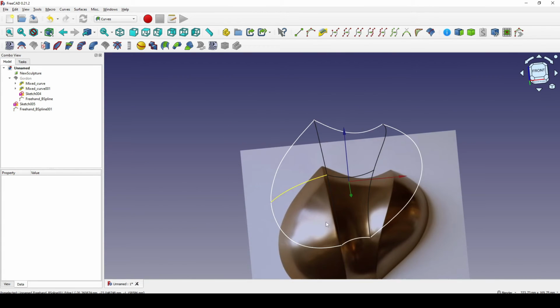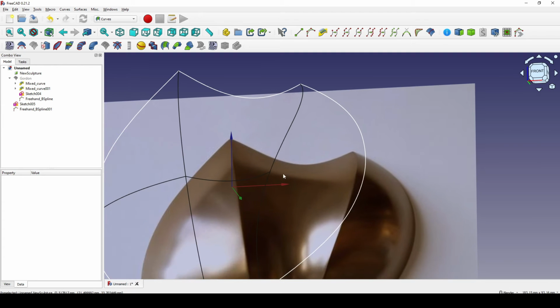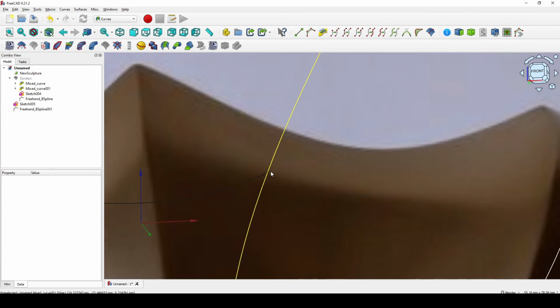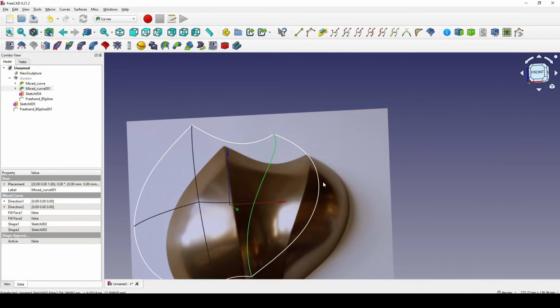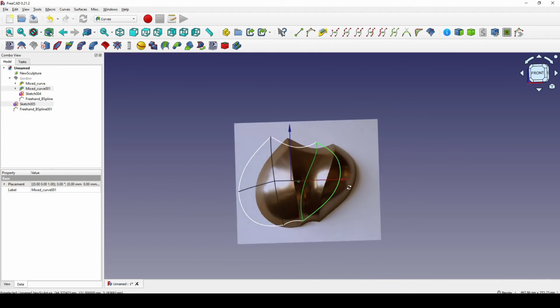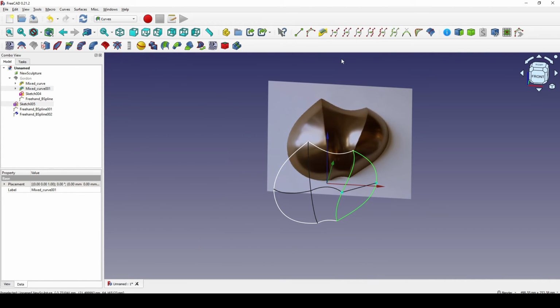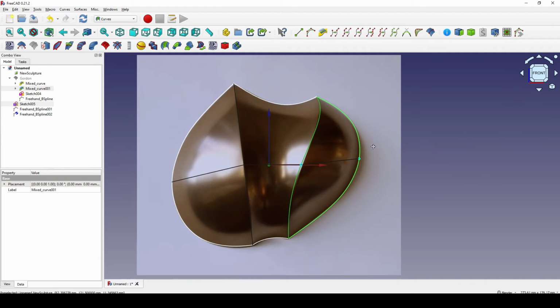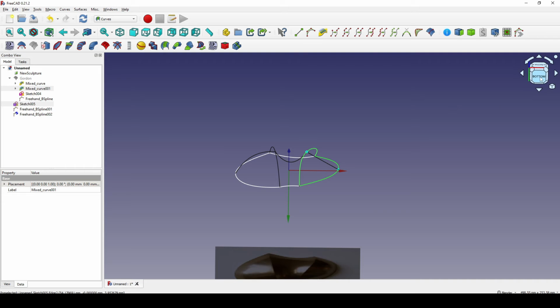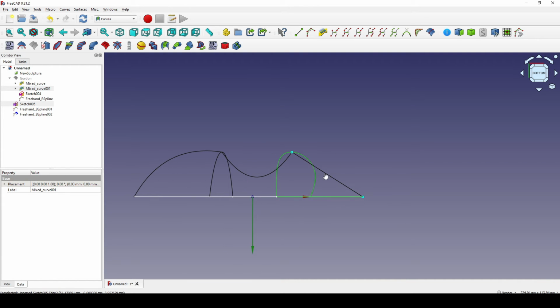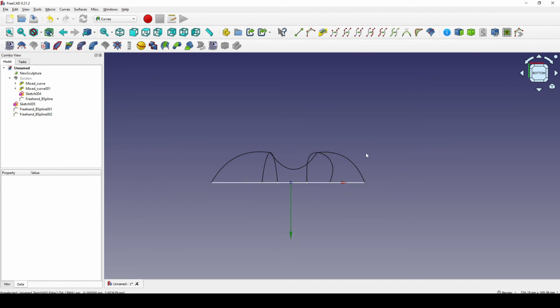Alright, something like this. Doing the same over here, you select somewhere close to this point and control select this curve in the middle, create a freehand display. And also I go to the bottom view and select this freehand display, hit I, and also this one, move this one up, hit Y to constrain it on the Y axis. I hit Q to confirm.